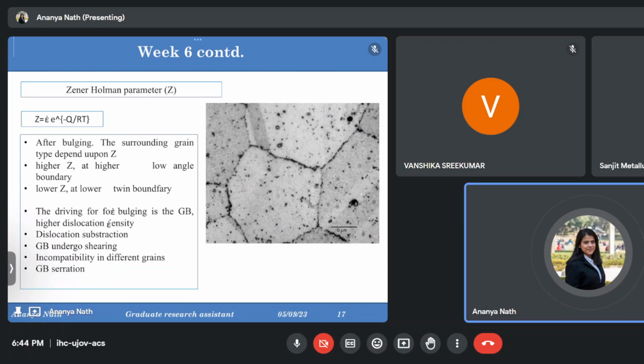It's not like one dislocation is moving. In recovery, all the dislocations have gathered at one place, and now at the time of recrystallization, they are moving all by themselves as a bunch. So one dislocation is not moving, and we do not want this to happen. So this is why we want the SFE to be low.